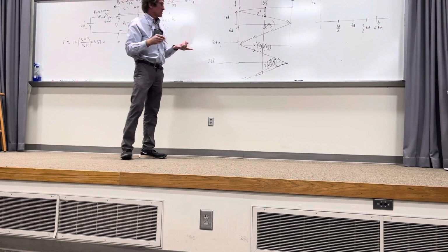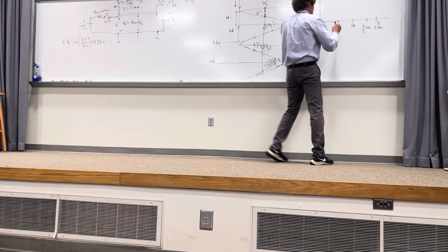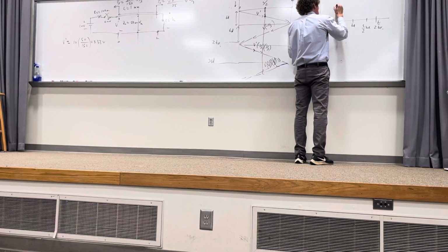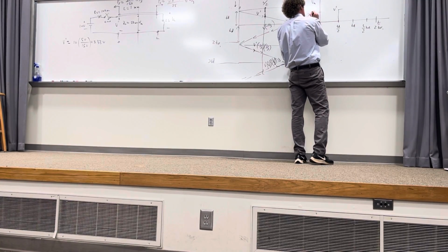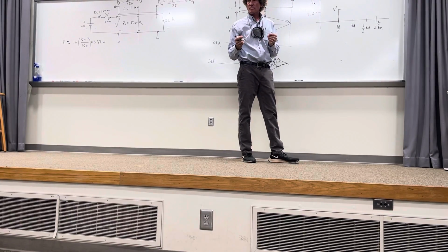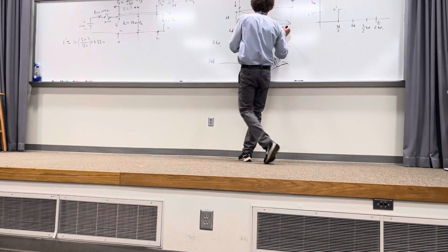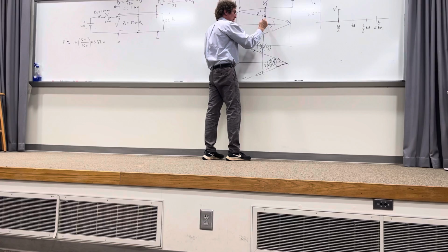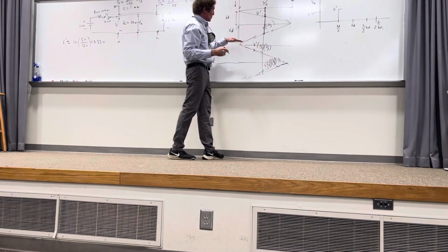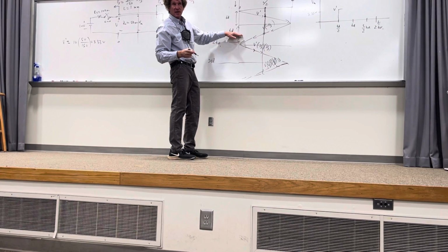Now when I hit here, that's the voltage that was propagating, so it just becomes V prime. And I know that V prime here is actually 3.33 volts, correct class? It just stays at 3.33 for how long? Well, you keep going down here and you see the next time this ricocheting pulse hits is down here, which would be at 3/2 TD. Do you all agree with that?